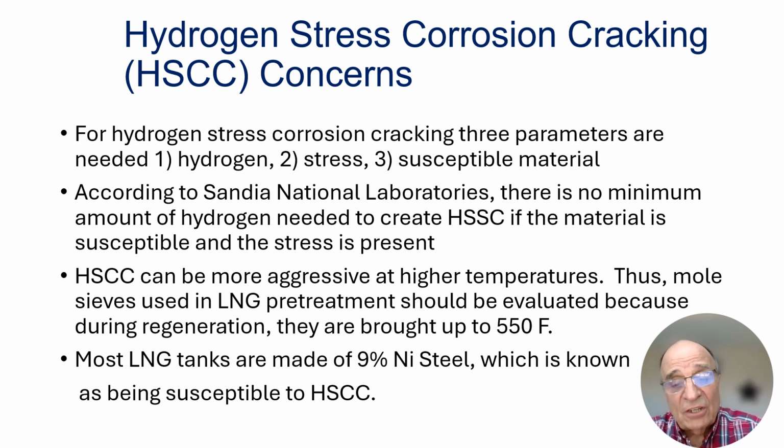Most LNG tanks are made of 9% nickel steel. That is the inner container of the tank itself. 9% nickel steel has been identified as not being compatible with hydrogen because of stress corrosion cracking. However, what's unknown is how it behaves at very low temperatures, cryogenic temperatures. That's where more research is needed. In conclusion, a lot more research is going to be needed for hydrogen within LNG facilities.